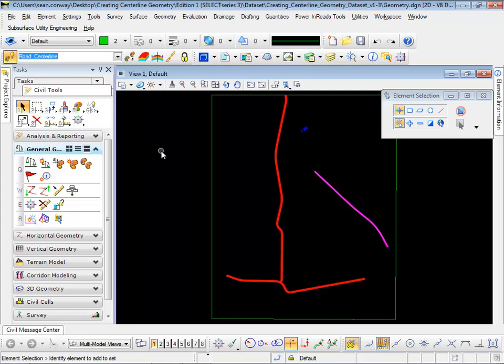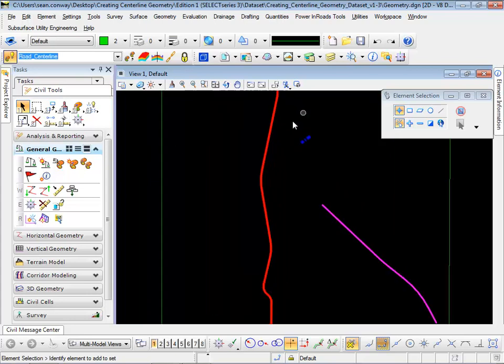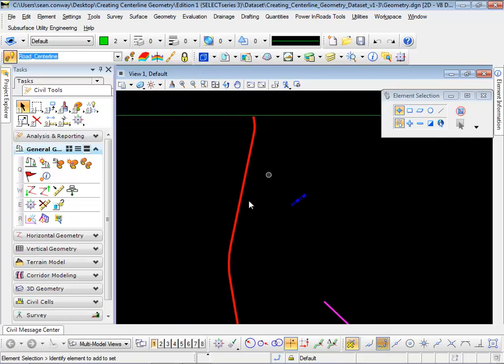We're going to zoom in to the north end of mountain highway geometry. So you can zoom in to the north end of this mountain highway, which one's north-south, and we want to enable Civil AccuDraw down at the bottom. So I'll toggle that on.